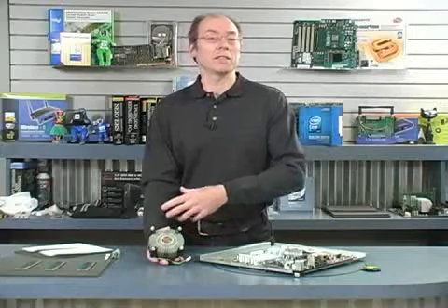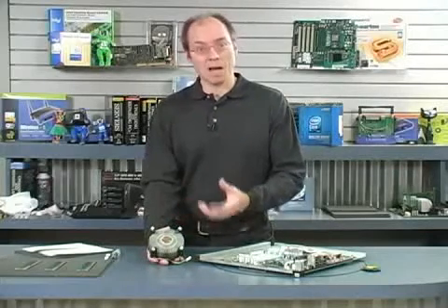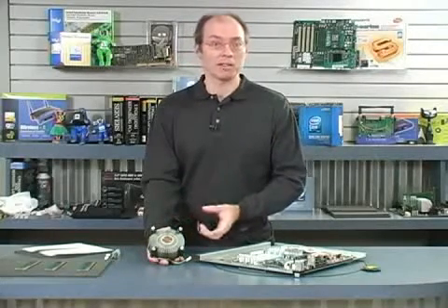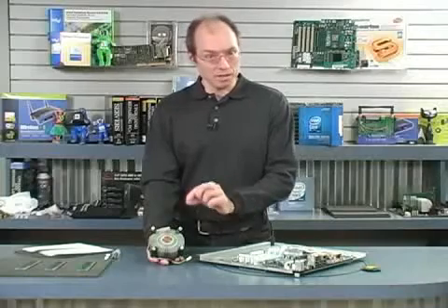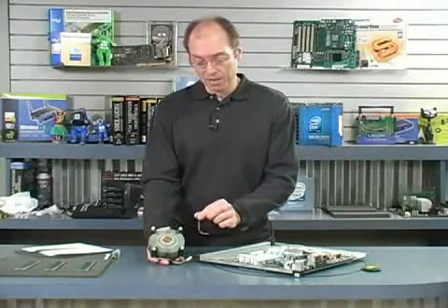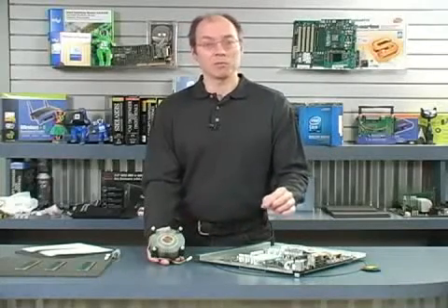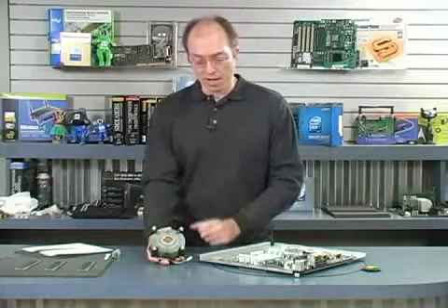So why don't we see heat sinks that are all copper? Well, the problem is copper is expensive. It's a lot more expensive than aluminum. It has twice the thermal conductivity of aluminum, but it also costs from 3 to 9 times more, depending upon whether you're going by weight or volume.